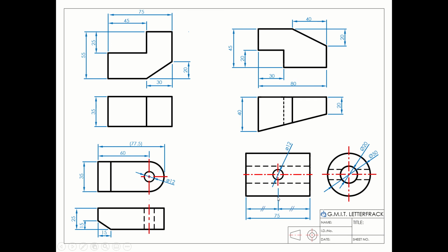And if you wanted to do that graphically, you could just put in a center line like that. I would be less inclined to put the center line like this in this case rather than the plate piece, purely because when we see it like this, it's obvious that this center line here indicates that this square here is kind of turned. It's not a square, it is actually cylindrical in shape. So I think if you add the actual center line there, it takes away a little bit from that. And again, that's a judgment thing. It's not incorrect, it is just down to judgment, but I would say that probably is a bit easier to understand in this particular case because it's a cylindrical piece.